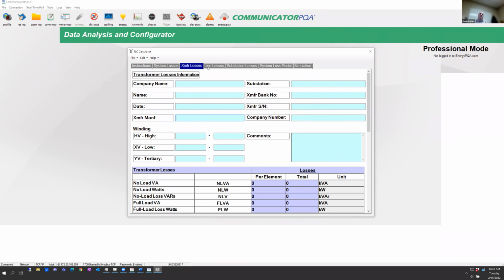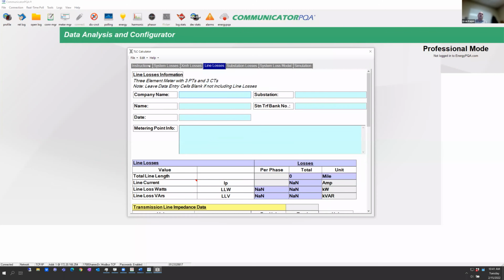the power transformer. So if anybody doesn't know what transformer loss compensation is, transformer loss compensation allows you to meter on the secondary side of a power transformer. So if I'm a utility and I'm bringing in a main feed of 14,000 volts to a big industrial manufacturer, well, I'm going to put a big power transformer there. And my power transformer is going to step that 14,000 volts down to, let's say, 277/480. And at 277/480, I'm going to feed it into the building. Okay, that's great. The utility would rather meter, and you would rather meter, on the secondary side of that transformer,